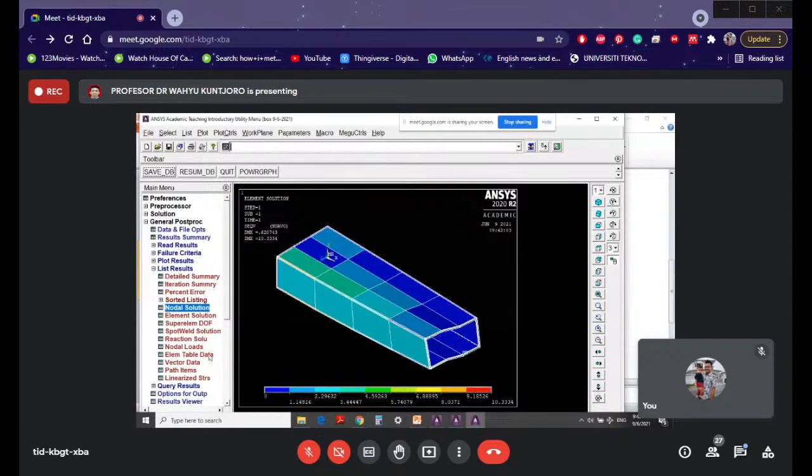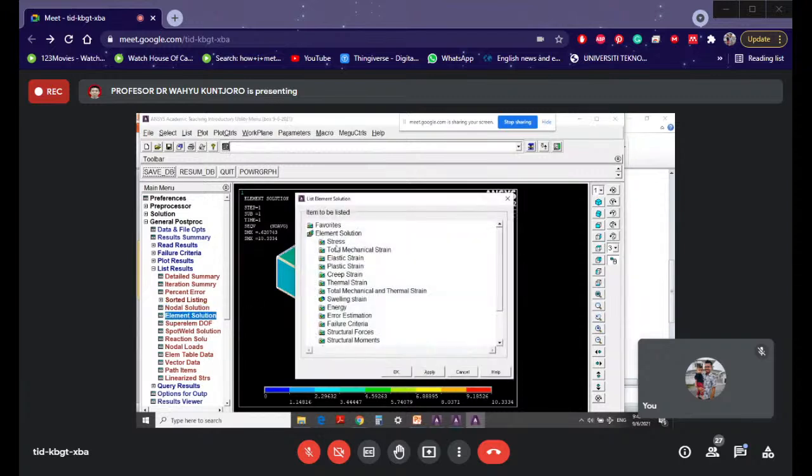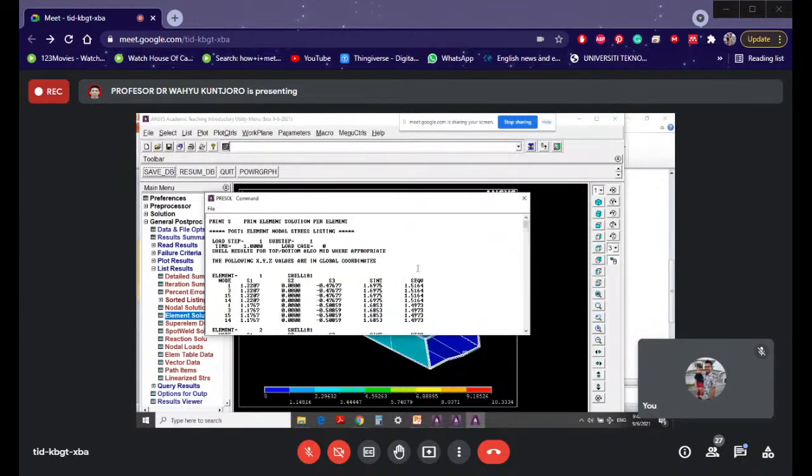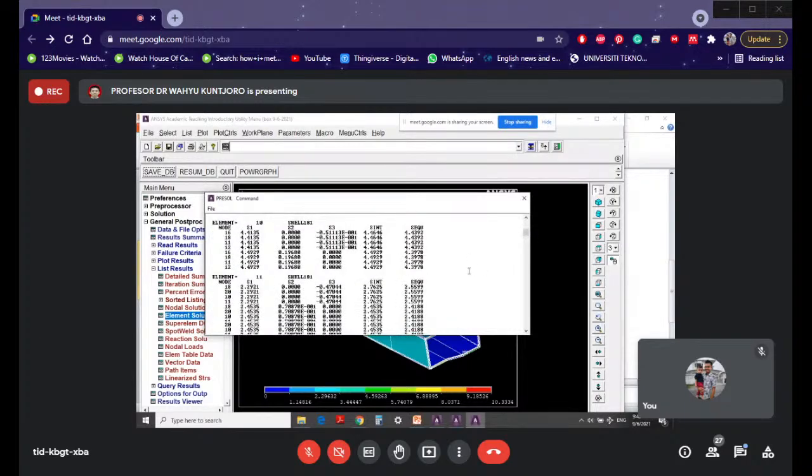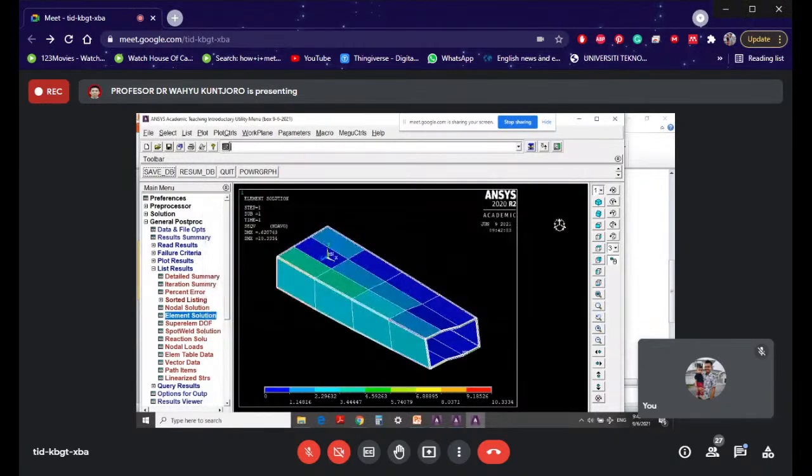You can also have a look at the element solution, stress, for example, von Mises stress. Then for every element, you will find your stress over here. Okay. All right. So with that, then we finish our